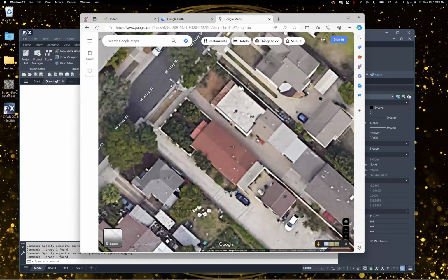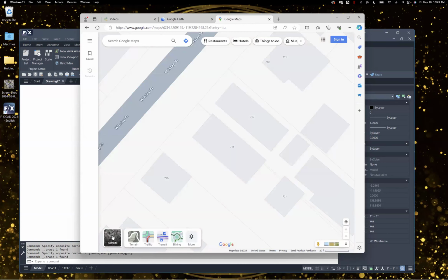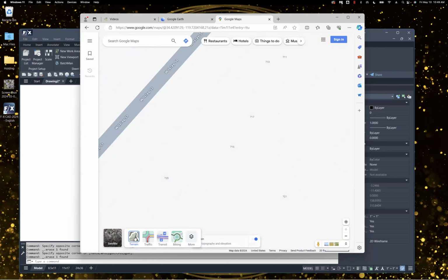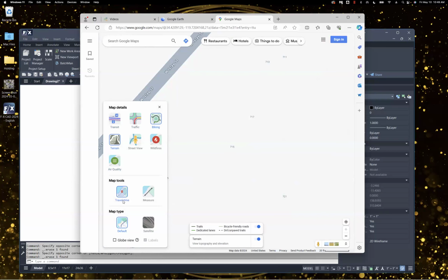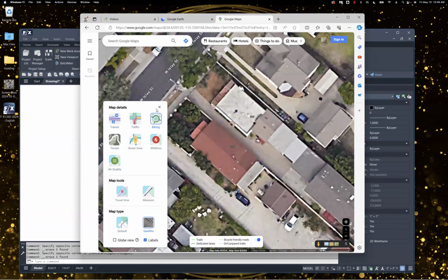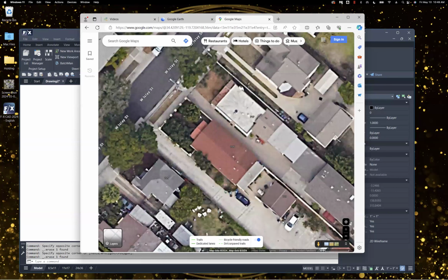Google Maps is worth noting too. You can see down here, on the bottom right-hand corner, it's set to feet. That's why I'm highlighting this, because in my own testing I didn't notice that right away. That is a difference. But again, much like the AutoCAD geolocation tool, you can change your layers here and get the different types of layers that you want, and you might experiment with some of those. We'll just leave it on satellite because it's pretty comparable.